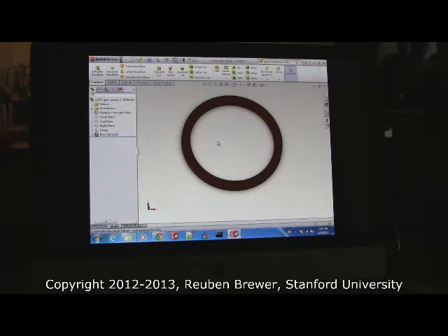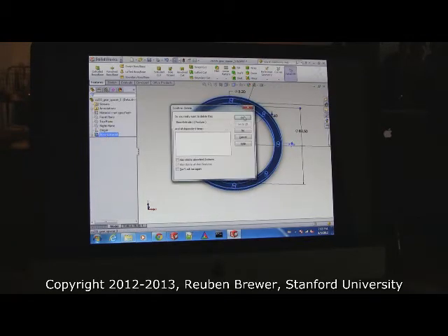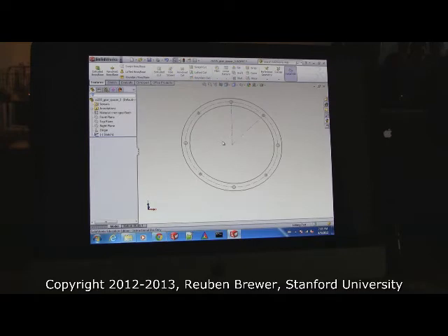Now say that you couldn't do Control Z. Go ahead, click it again, and hit delete so you're left with just a sketch. If for some reason, say we saved right here and we can't Control Z, well, it's the sketch. We didn't lose any information. All we lost was the axial extrude direction.